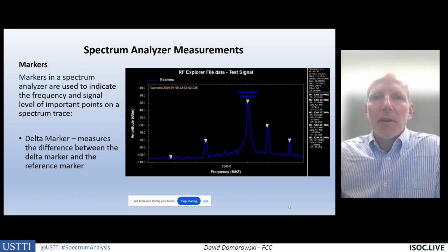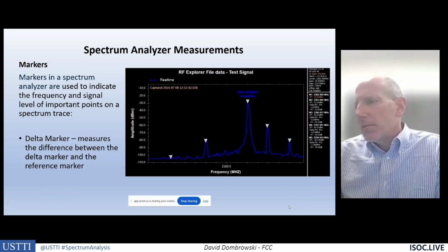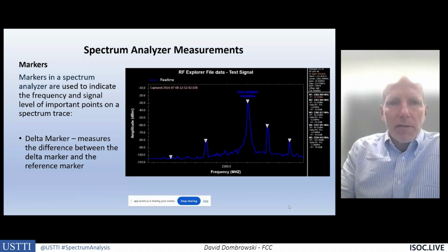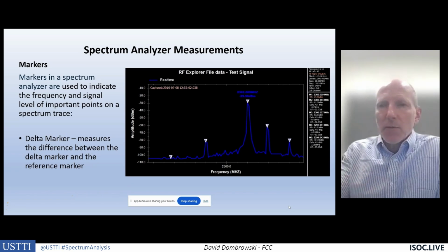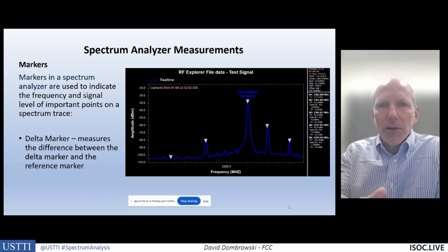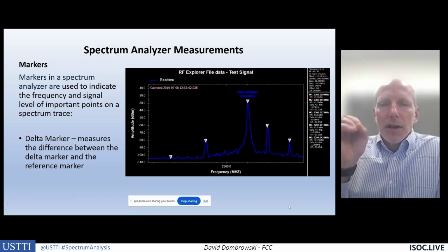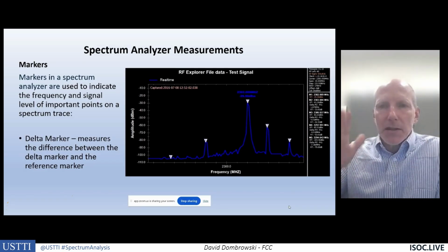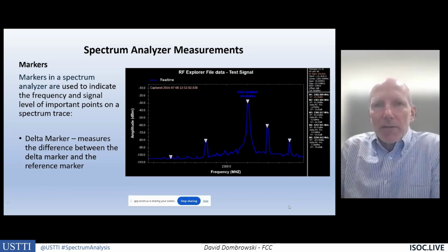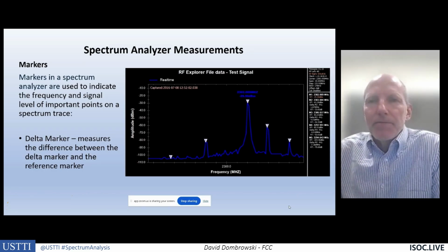Those same things can happen in radio receivers, because a spectrum analyzer is somewhat of a radio receiver, a little bit different. But some of the problems that get generated, intermodulation, that's typically what we'll see when we create our own interference at a site. The best way to eliminate that is to put a bandpass filter, so I'm passing just the frequency that I'm transmitting on, and I'm reducing the emissions from other transmitters coming down into my antenna.